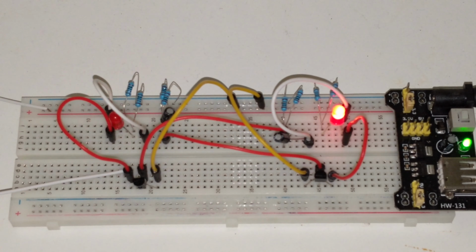And it is not just about the components of the circuit. The availability of components and tools that you use, the breadboard, the connecting wires, the quality of soldering, the power source, the ambient temperature of the environment, and many such parameters impact the outcome of the design. You have to design circuits to be tolerant. One example of such a circuit is the LED driver we examined in the previous videos. It can take a wide range of input, anywhere from 175 volts AC to 265 volts AC, and convert it to a fairly stable output of 250 milliamperes DC to drive the LEDs.